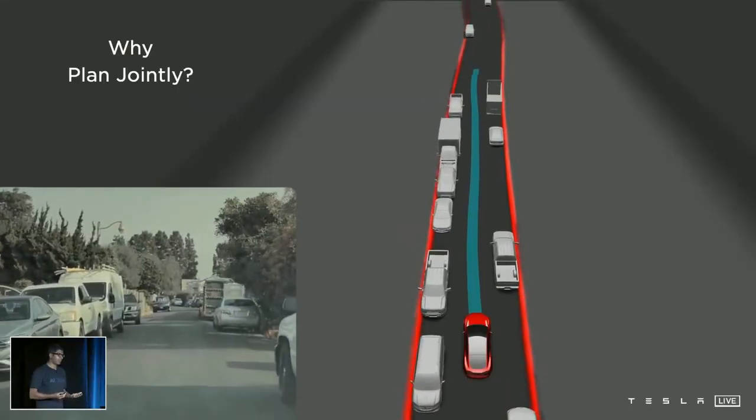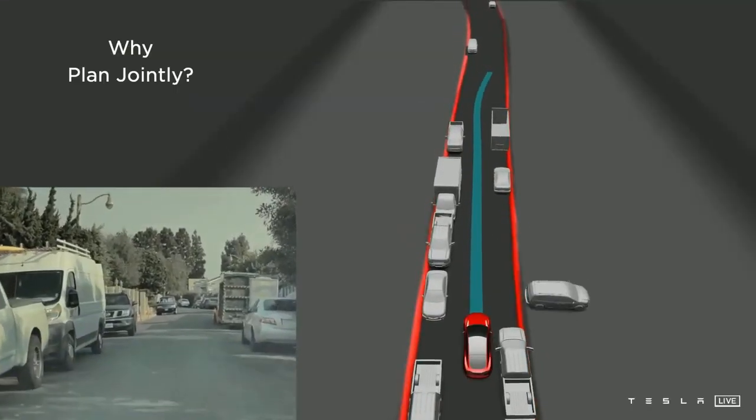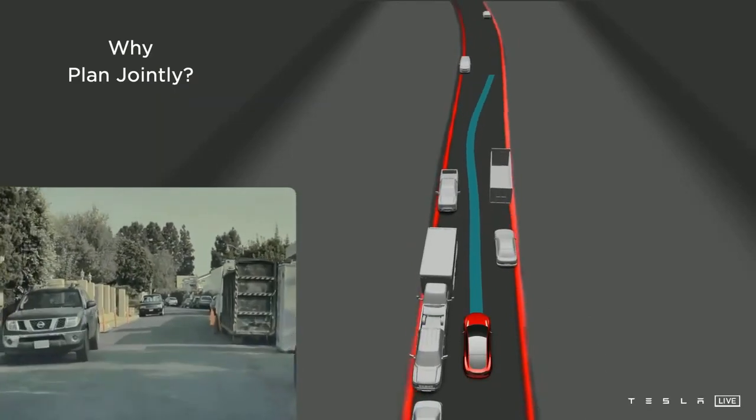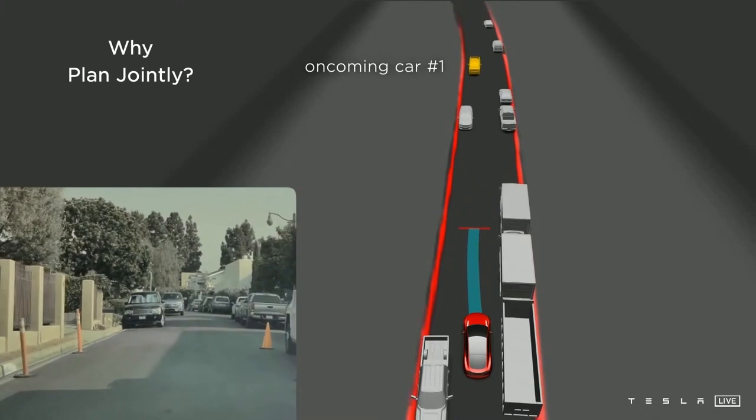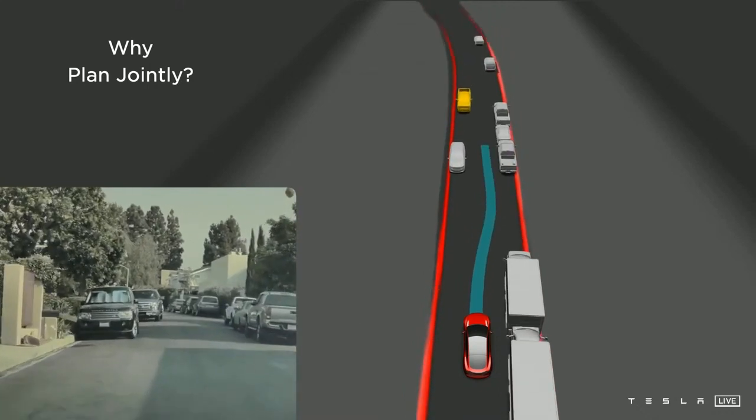Yeah, that was autopilot driving in a narrow corridor, going around parked cars, cones, and poles. Here, there's a 3D view of the same thing. The oncoming car arrives now, and autopilot slows down a little bit, but then realizes that we cannot yield to them because we don't have any space to our side. But the other car can yield to us instead. So instead of just blindly braking here, autopilot reasons that car has low enough velocity that they can pull over and should yield to us because we cannot yield to them, and assertively makes progress.